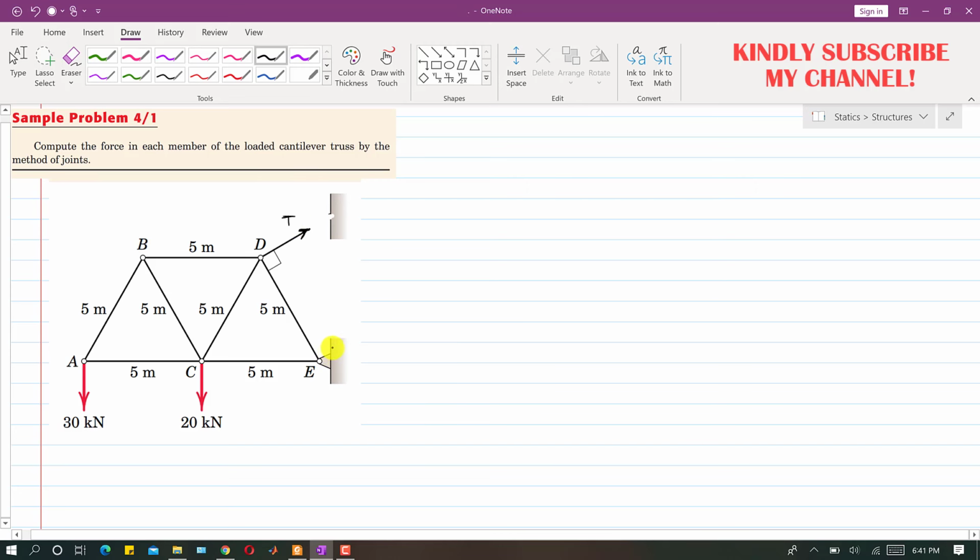And similarly we will have two reactions at this point E. One reaction will be in this direction, and one reaction will be in this direction. Let's say that this is our positive x direction and this is our positive y direction. Then we can say that this is Ex and this is Ey. First we will find this T, Ex and Ey, so for that we will apply the equilibrium condition.